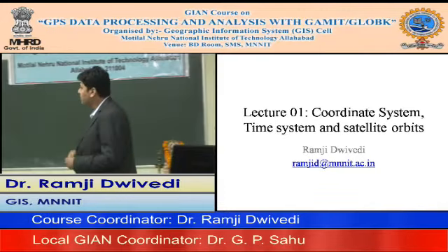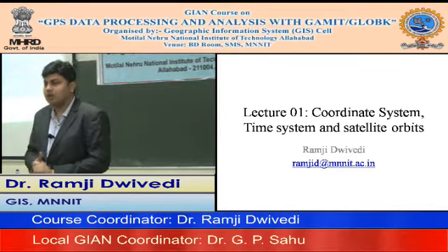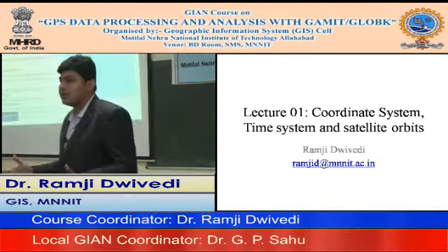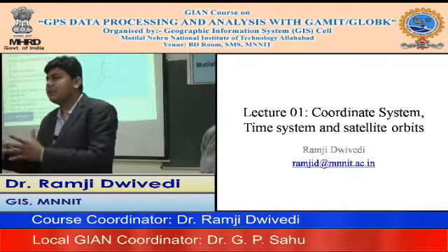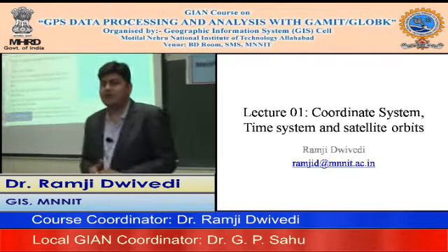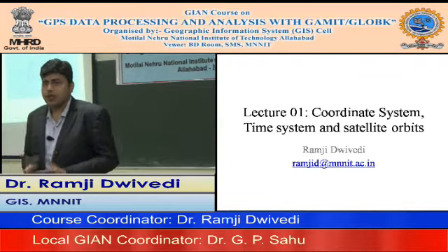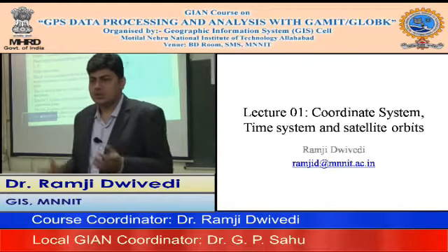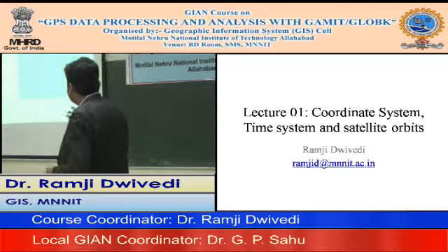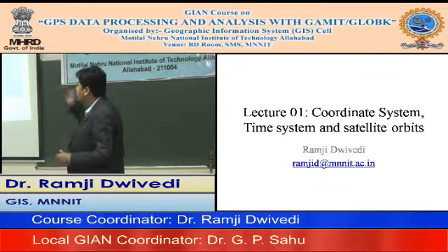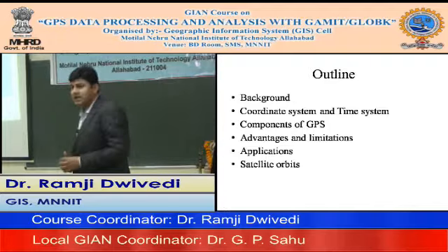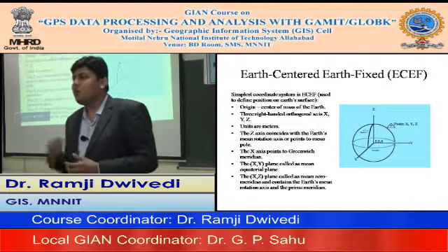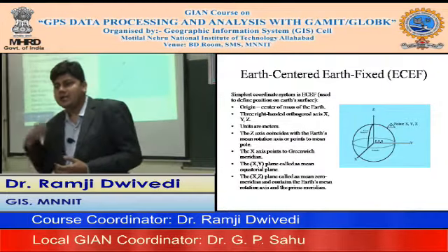Many people want to know which coordinate system we are working on, but before that, you have to identify the Cartesian coordinate system, because many of you in your 11th level or intermediate level only understand coordinate geometry. You don't understand whether it is related to the earth or to anything. You just have a coordinate. So for coordinates on the surface of the earth, the simplest coordinate system is earth centered, earth fixed. One reason for having this system is that you don't want your position to change as the earth rotates.